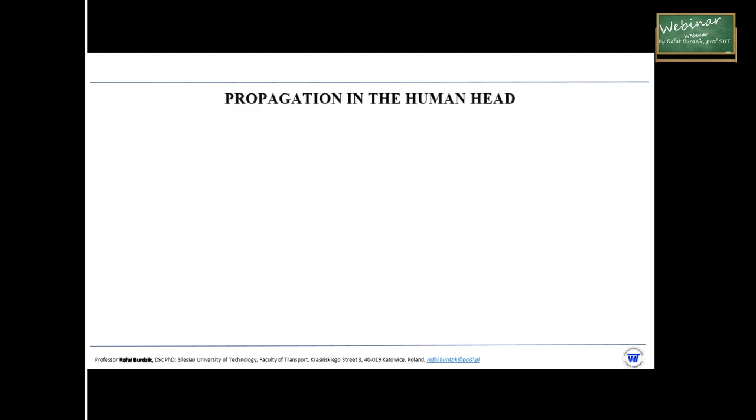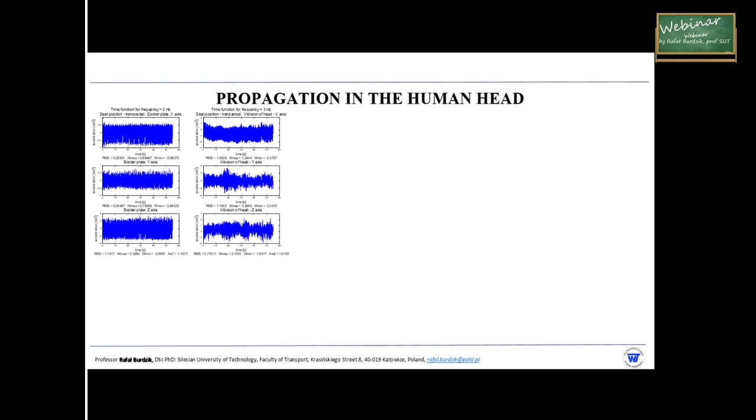And the next results which I would like to show you are the propagation into the human body, for which I chose the next frequency, which is 3 Hertz. So it is, we can say, the upper part of the frequency band corresponding to the sprung mass resonance, which is also important to comfort. So it is the excitation plate, the knee.